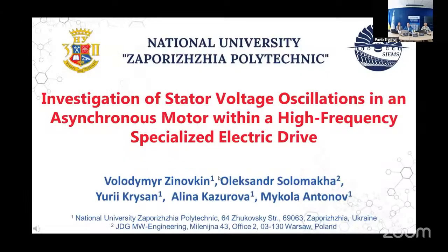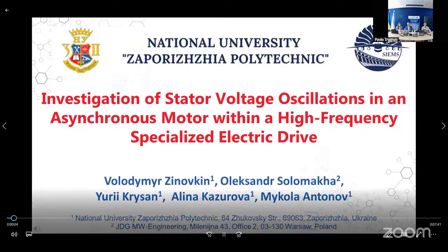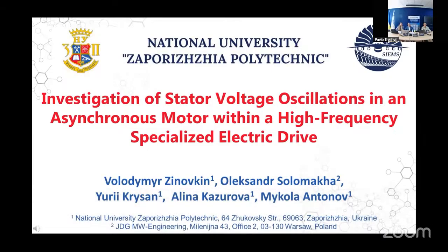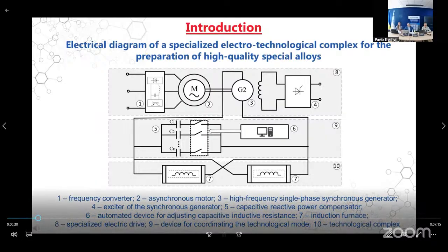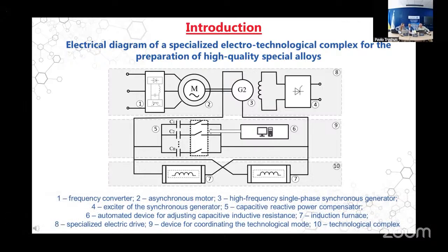Dear participants of the conference, let me introduce to your attention the report on the topic Investigation of stator voltage oscillations in an asynchronous motor within a high-frequency specialized electric drive. High-quality steels and alloys are manufactured in specialized high-frequency induction technological complexes. The main elements of such complexes are the induction furnace, capacitive reactive power compensators, switching devices, and primarily the specialized electric drive. It consists of the three-phase asynchronous motor and a single-phase high-frequency synchronous generator.